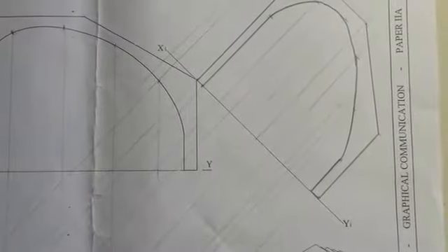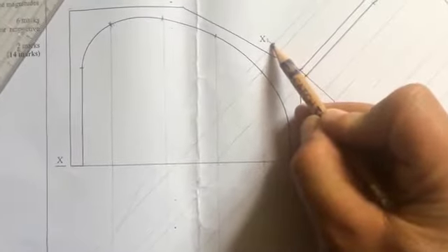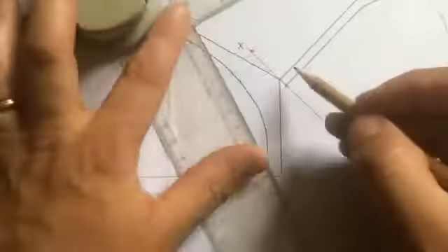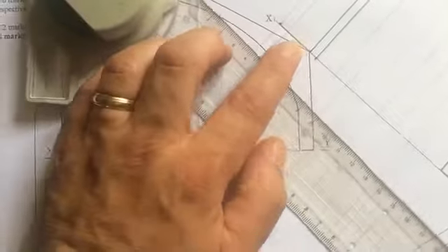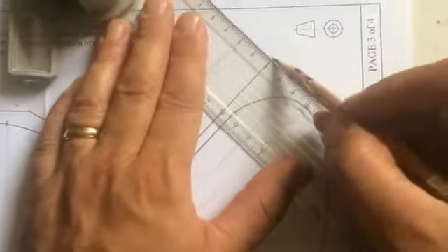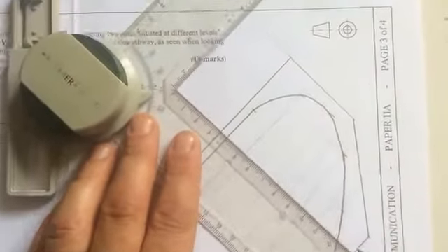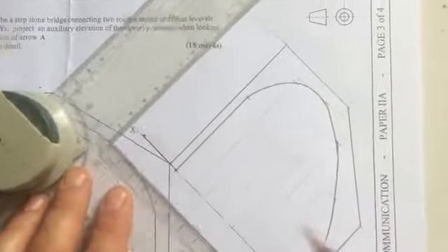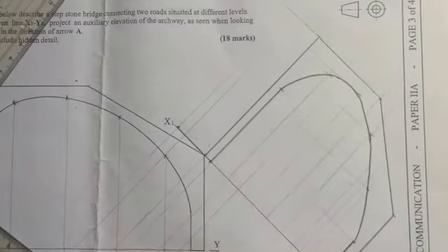Now I need the back face, because this is seen at an angle. You're going to see its depth. Its depth you can see from this point here. So I'm going to have a depth of up to there. Now as I've shown you in the other examples, once you find one depth, all you need to do is project each point that you found at the same angle as the XY line.